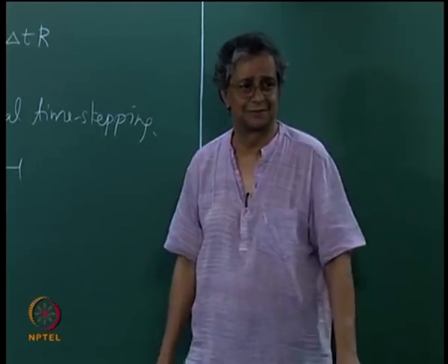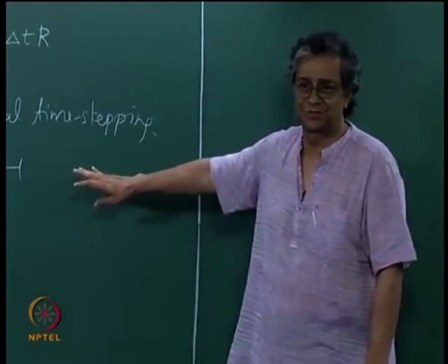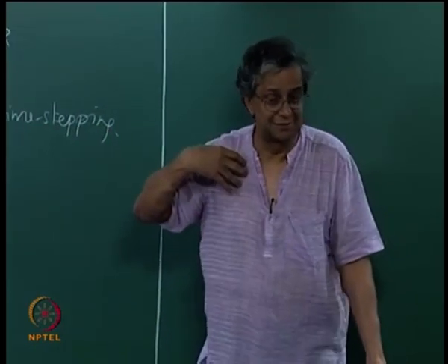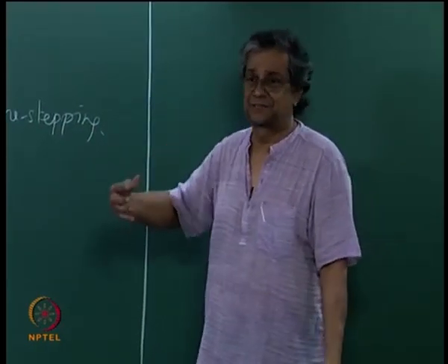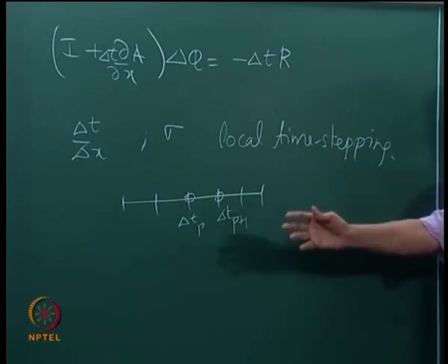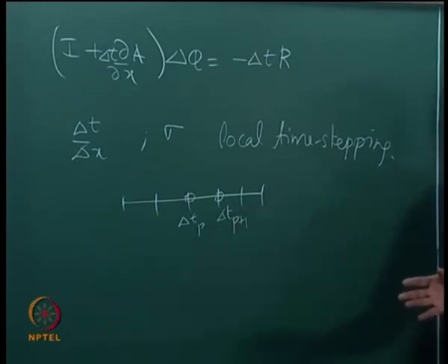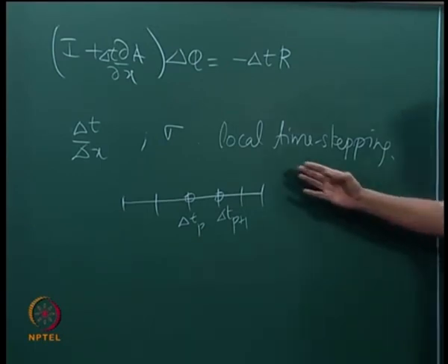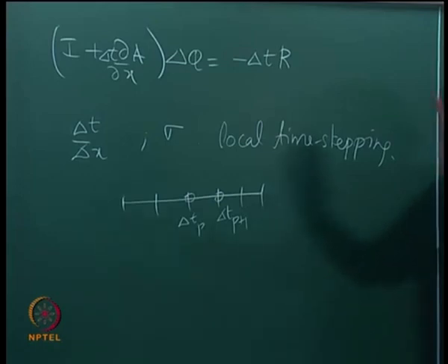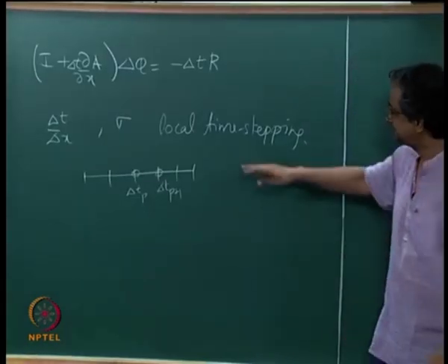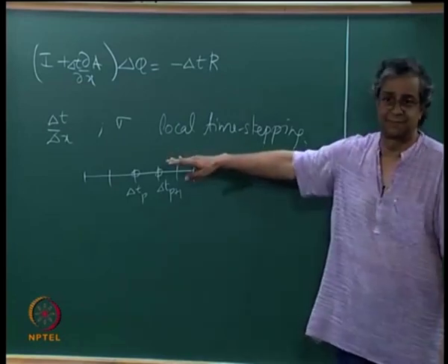So I don't care. And if it gets to the steady state solution that I want faster, my experience has been that you do get to the steady state solution faster. So if I am looking for the steady state solution, I am likely to do local time stepping, right? In my experience, you do get there faster, so I am going to do local time stepping. Am I making sense? Okay. So this is one possibility.